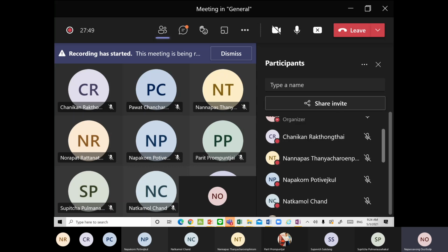So repeatability, as we have talked about before, means the variation from the measurements of the same part. The keyword is the same part, and also the same operator. Operator here means the same measurer, the same one who does the measurements. So repeatability means the variation of different times that each measurer measures the same part.